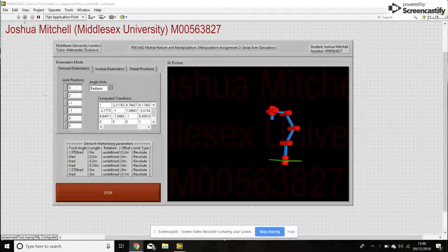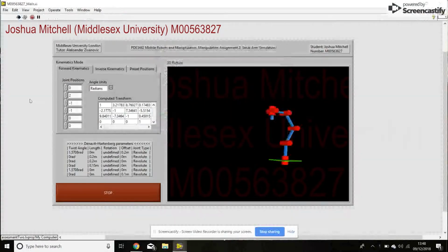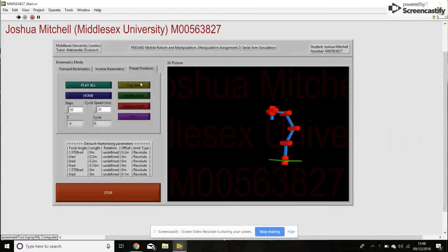For this video, I'm effectively going to start at the end product of the project, working with this tab. For the project, we had to design the Denavit-Hartenberg parameters of a robot that was capable of mounting on a turtle bot and reaching the 4 positions that I'm showing you now. The only specification given for these positions was the height, which is why I'm only showing the Z coordinate, required at 0.2, 0.6 and 0.4 meters from the floor.